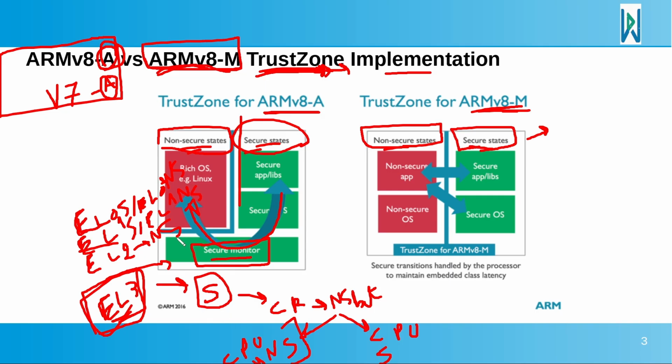However, it will impact the state of the CPU while running in exception level 0 or 1. Hence, if we jump from exception level 0 secure to exception level 3, then we set this bit to 1, then we return back to exception level 0. This time the CPU will be in non-secure state, and hence will be executing in exception level 0 non-secure.